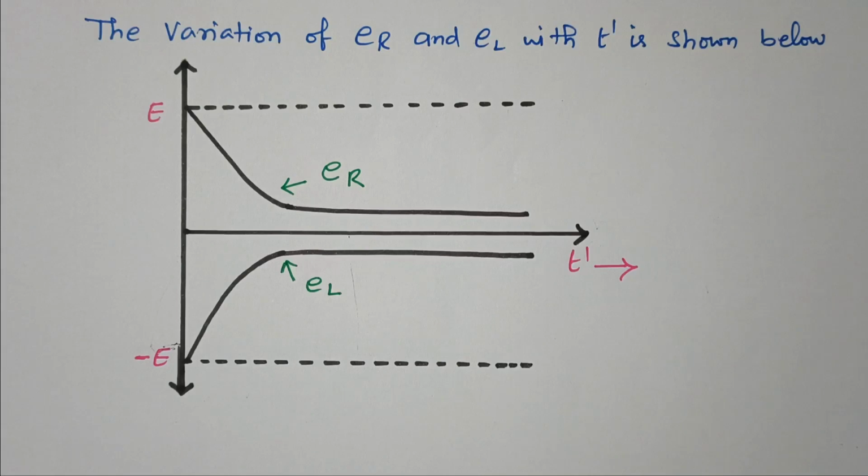So in this video we discussed the DC transient response of the RL circuit. In the case of decaying, we identified that the current I of t is decreasing from I to 0 when the time increases from 0 to t. And the voltage across the resistor and inductor is also decreasing, the inductor in the negative region.